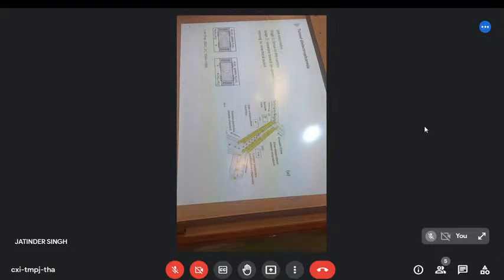The other particles don't experience enough force, kind of slowly moving away, but very slowly. And in the time it takes to go from the start of the second dimension to the end of it, they haven't made it to the middle of the channel yet, which means that they leave the fluidic system down through the other outlets. So we started with a chaotic mixture. We first use a kind of a broom. We use a dielectric field that swipes up all the particles and gets them nice and close to the wall.